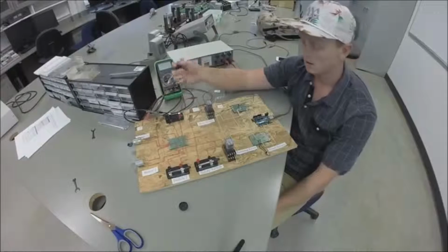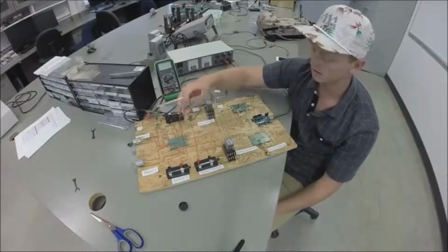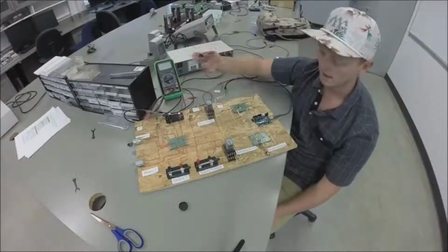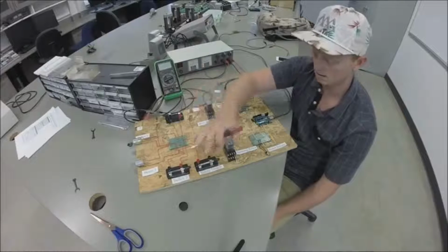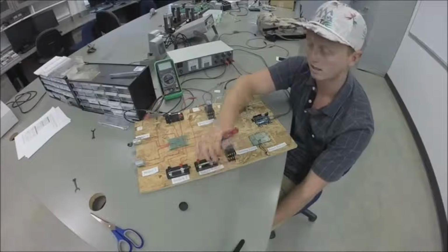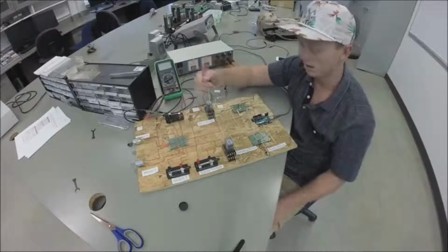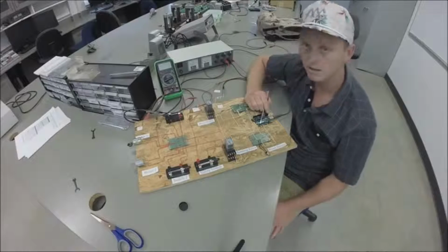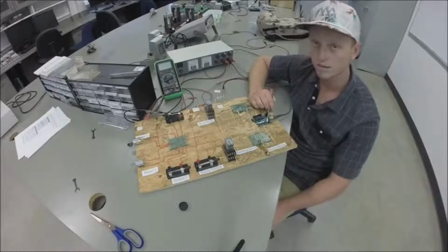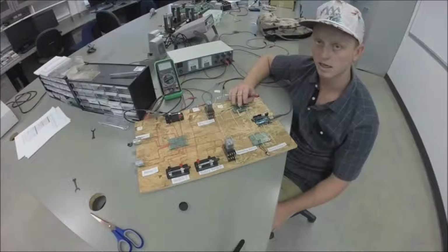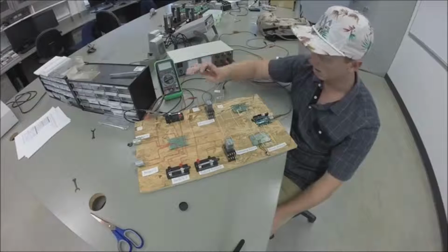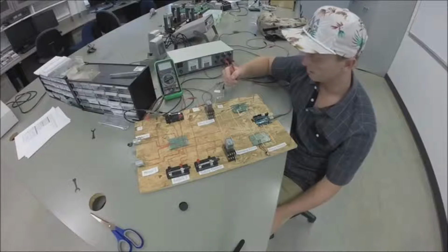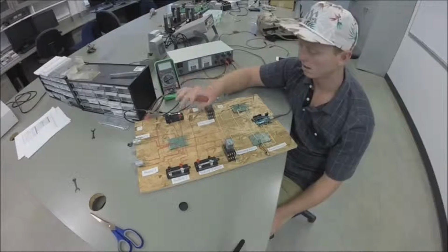Normal plant, everything's in normal operation. You have power coming in through your main relay, into your motor controller, and going to the motors, and everything's spinning perfectly. All of a sudden you have a major spike. Your sensing relay is going to sense that across your motor controller, which then causes current to flow all the way back to pin number 2. Pin number 2 sees a signal, which then cuts off power to pin 13, which then opens up the NPN transistor, which then stops flow of this circuit, the positive 13 through the transistor out, and cuts power to your motor control.